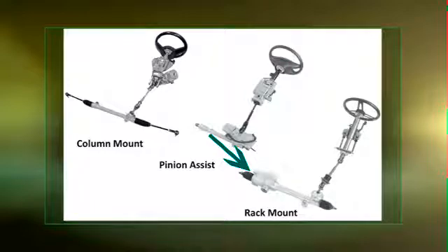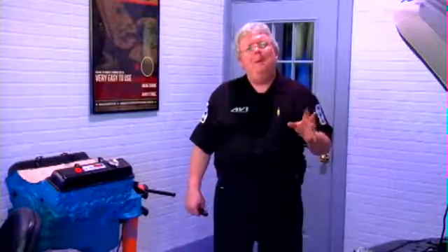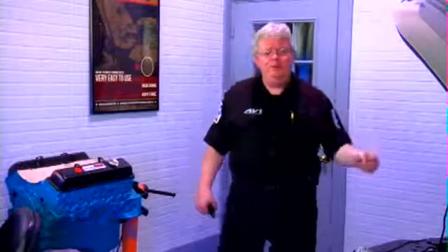Now it's interesting that on the hybrid Tahoes and Escalades, what GM calls their two-mode hybrids that they've had for about the last 3 model years, those use a 42 volt power steering system because you have high voltage of 300 or more volts in the hybrid system. They say, hey, we'll just drop it down to 14 to charge the battery through our DC to DC converter, and we'll drop it also down to 42 so we can have a little extra edge of steering that vehicle with a little bit more muscle electrically.